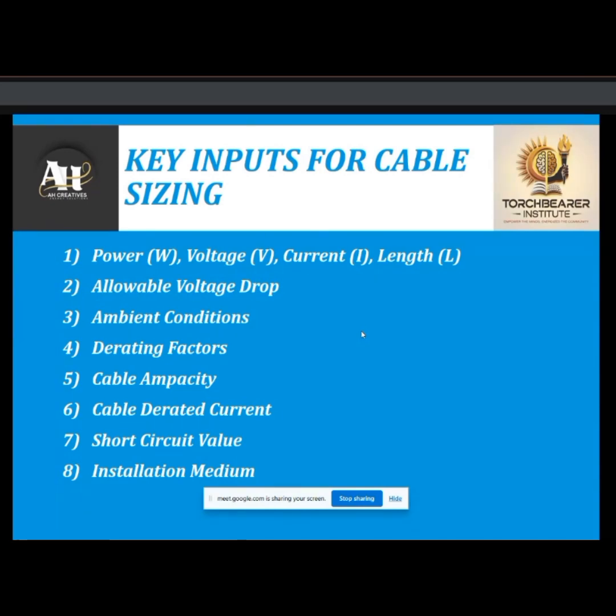And the other one is the length of the cable. The length of the cable is very important. Basically, the length of the cable is used for the voltage drop calculation. When the cable length is higher, the voltage drop is higher. So that's why we have to maintain the voltage drop within permissible limits. We use the length: if the cable length is on the higher side, we increase the size, the area of the cables, like where we are using 185 square mm cables and the voltage drop is 2%, but we have the limit of 1.5%, then we use the 240 square mm cables.